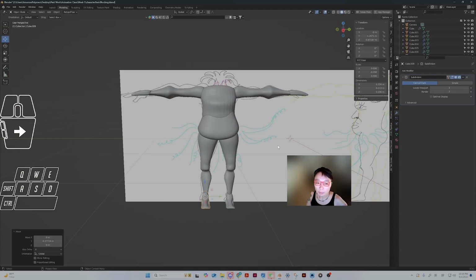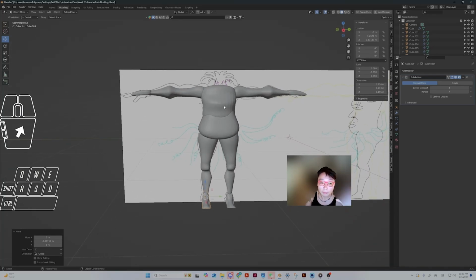So to wrap up, the assignment for this class: I would like you guys to make the reference drawing. Remember, the reference drawing is frontal and profile, and then learn to load it into Blender. And I would like you to practice what I talked about with manipulating, so importing a cube and then manipulating the vertices, edges, faces, doing beveling, and using these tools, seeing what shapes you can create. And then using basic geometry, the method that I introduced, block out the basic shape for the body.